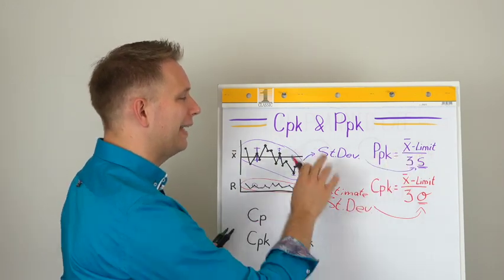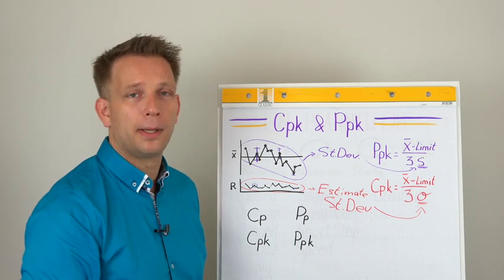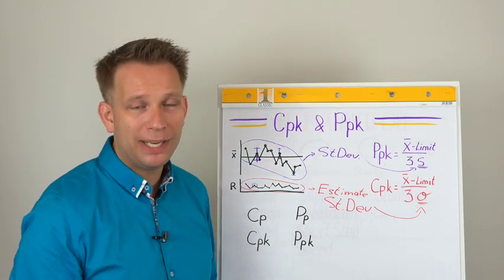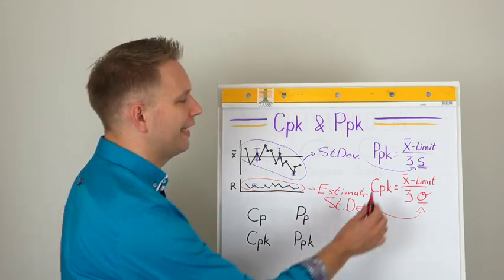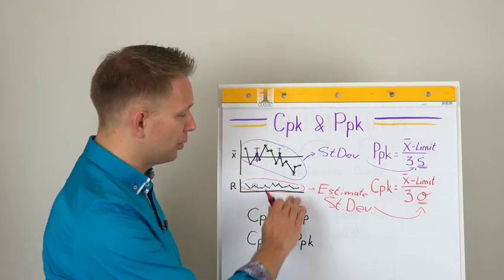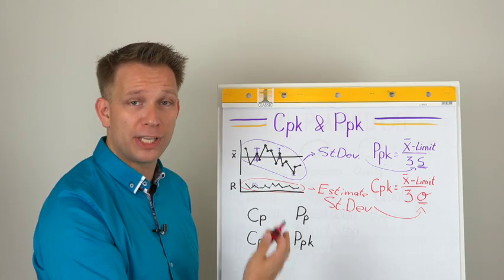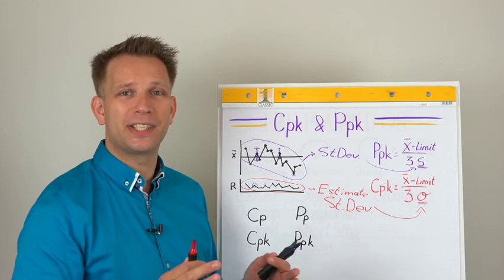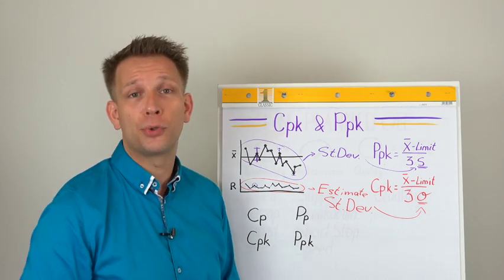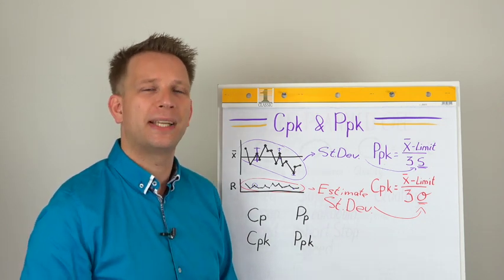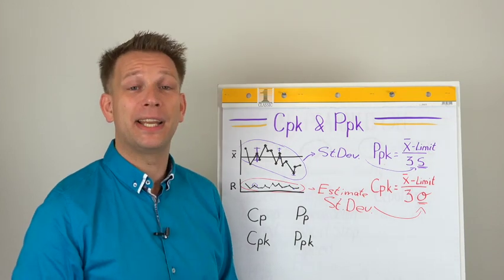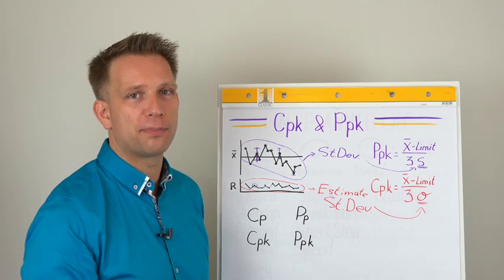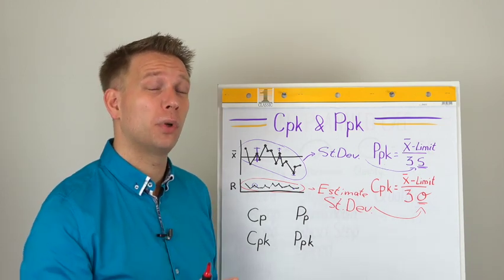Now, the Ppk does take all of this into account. What your client demands depends a bit on what they want. It is actually logical that they take the Cpk, because you will get them the average of your sampling for that batch, and this has to be within norms, and they want to know that the standard deviation of the sampling is low so that they know that you took a representative sample from that batch that they are receiving. They are not that interested in the total process performance. That's more for your internal quality standards.